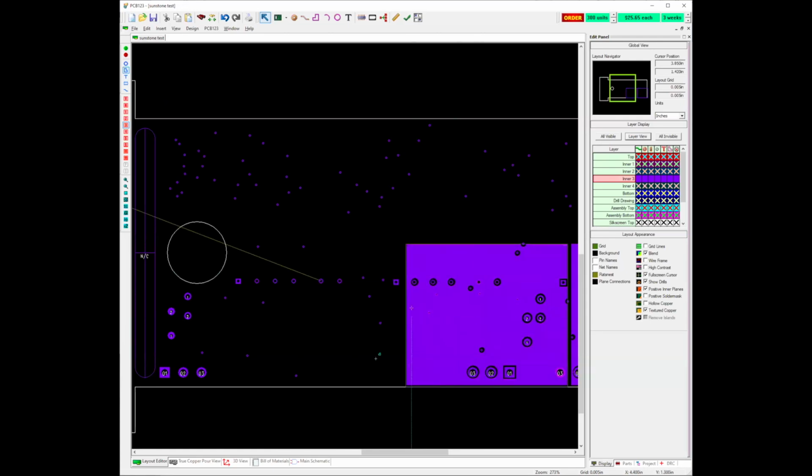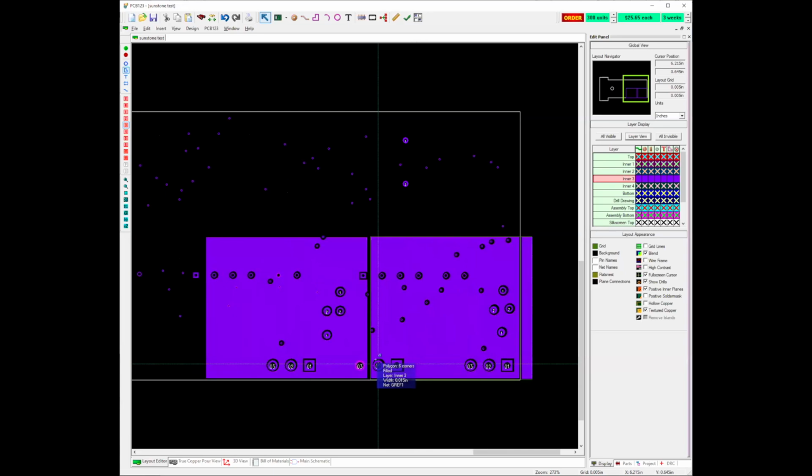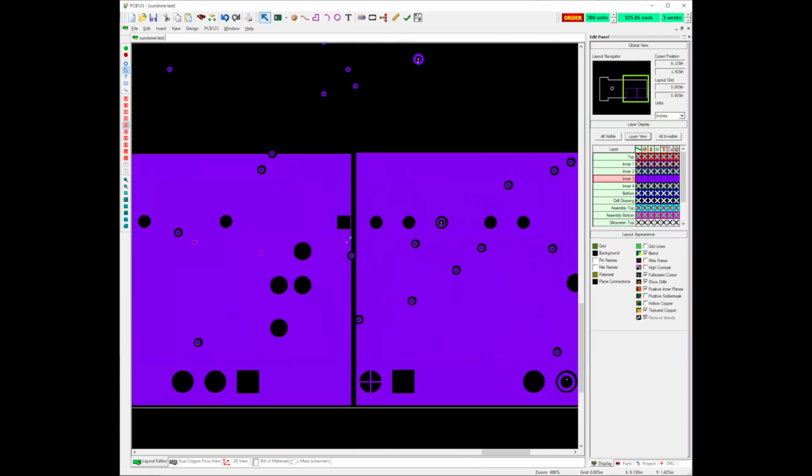But if you've got a pin over on the left-hand side of this that's not tied, and this is the only plane layer or plane that you've got drawn, it will give you a guide, and you'll have that opportunity to get it corrected, move your part over, or run a signal wire, a trace across the board to tie it to this plane. Some way of mitigating that problem. Again, questions? Was I clear or was I mud?